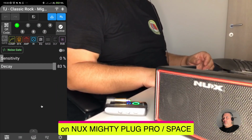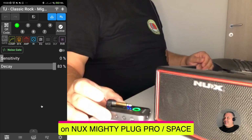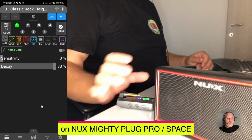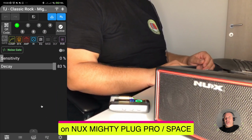It's a sort of whistle that makes it unbearable to keep the headphones on, and it is also related to the volume. If you decrease the volume, it tends to disappear. In particular, it is activated by some specific blocks. If you activate a compressor together with the noise gate and you keep the volume quite high, the outcome is a problem. It's something that you don't really want to get. So please make sure not to activate too many effects, and in particular, be careful when you activate the compressor.